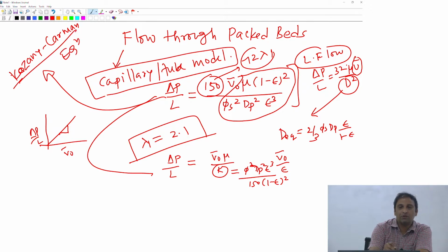That's because these people developed this equation. These developments happened in the 1930s and 40s. The fact that these models are still used in predicting pressure drop through packed beds is a testimony to the fact that these are very well thought out models. And typically when people do this modeling in chemical engineering, you take a particular process and put across a very simple methodology to evaluate, in this case, the pressure drop per unit length. The concept that this packed bed consists of tubes, and the concept of equivalent diameter, is not easy to come up with, right?